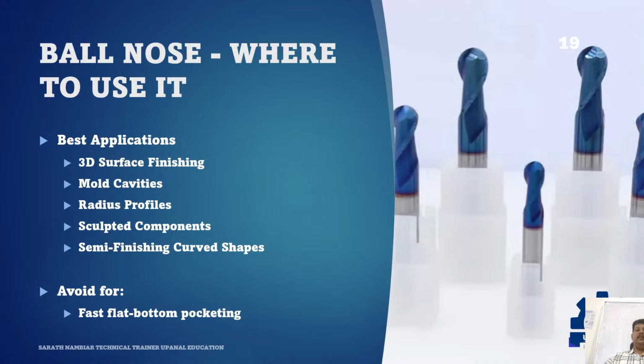Next, where is the ball nose used? Ball nose is used in multiple places. First, in 3D surface finishing. This is the most famous use. When the tool moves in many fine passes across a curved path, ball nose cutters help produce smoother surface planes. Second, mold cavities.